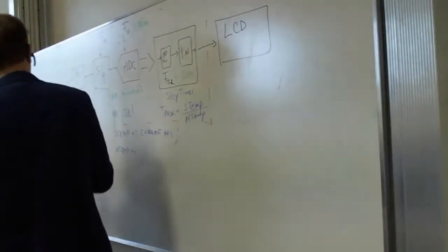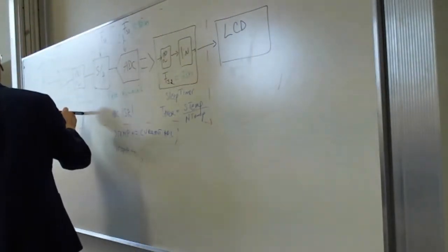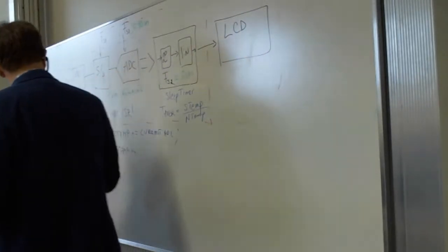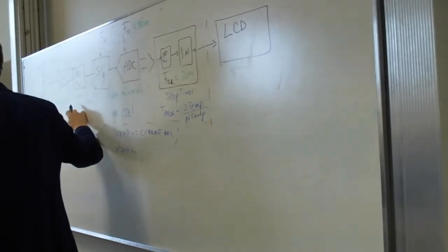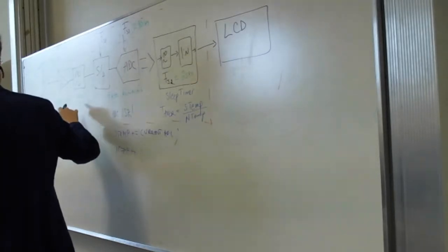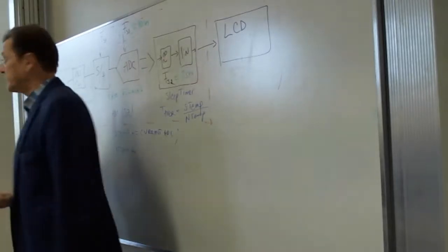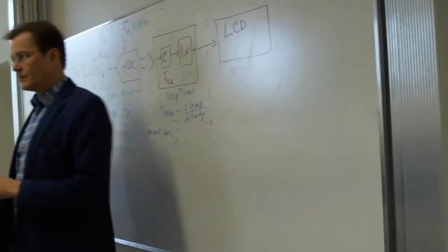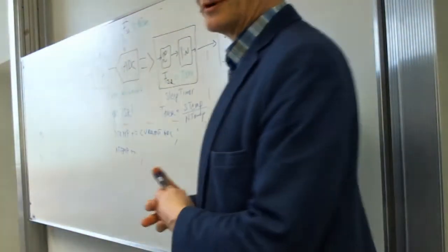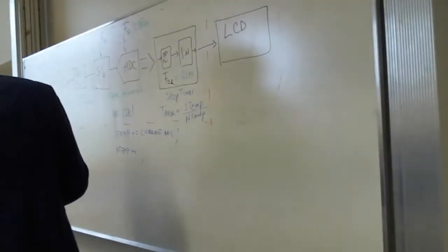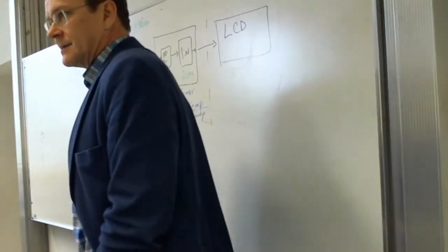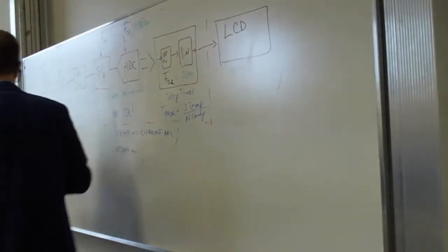Okay. Yeah. So amplifier, analog low pass filter, sample hold, A to D. For the exercise, I will put the analog low pass filter in parentheses, since that's kind of extra stuff. You can do it if you want to explore that point. This sensor is slow, so you don't necessarily need this analog low pass filter.